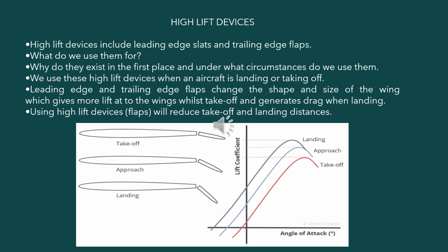and also the leading edge slat and trailing edge flap, deflected downward, increase the effective camber of the airfoil, which increases the lift. In addition, the large aft projected area of the flap increases the drag of the aircraft. This helps the airplane slow down for landing.